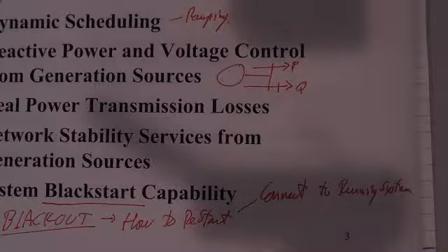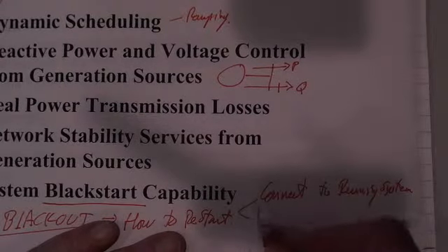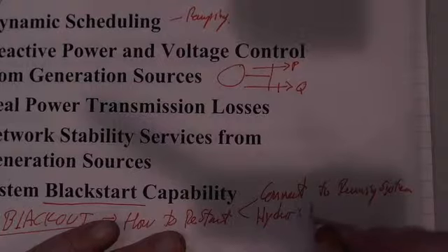If you're a hydro plant, probably you can do it. Now, if you only have that valve mechanism that I showed you before, well, you still need some power to adjust the valves. Now, if you had a chain or a geared mechanism where you could adjust the valve with a manual, let's say turning a crank or something like that, that would be very useful, because then the hydroelectric plant doesn't need an outside source of power in order to start producing power. So that's what's called black start capability. Hydro provides black start.